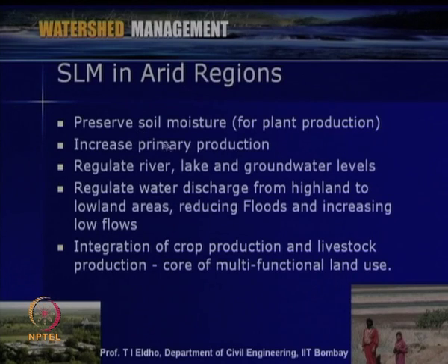And then we can increase the primary production, in terms of water or other resources. Then if any river is there, we can regulate the river, lake and groundwater levels, so that we can achieve sustainable land management in terms of watershed management practices. Then we can regulate water discharge from highland to lowland areas, reducing floods and increasing the low flows in the streams or channels.